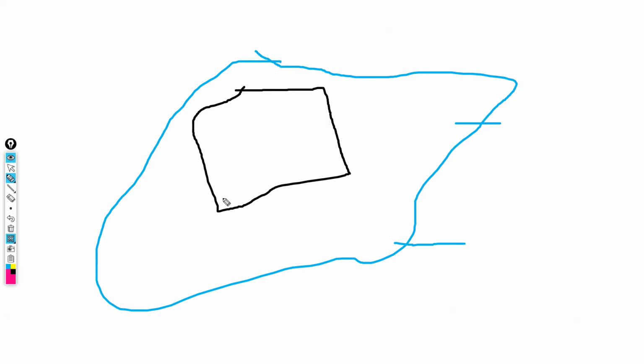Maybe they pick samples at this point, this point, and this point. So here you have 2 trial pits in the site. In each trial pit, you're going to have a surface exploration and also a subsurface exploration.